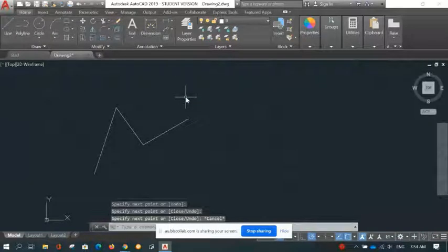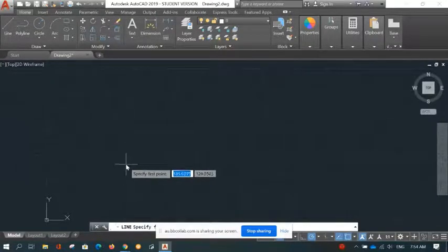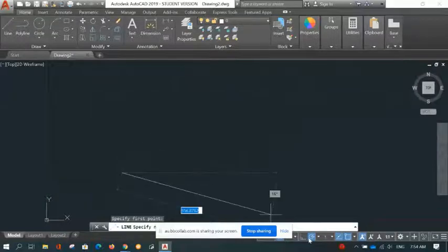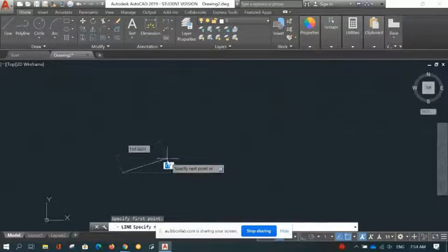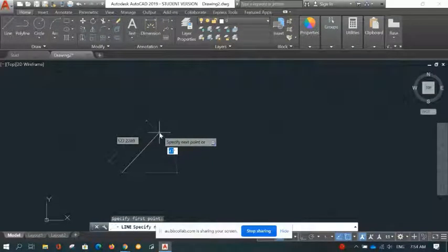But if you're using dynamic input, right, there's a box with blue text or numbers that appears on your cursor. So when you click, it's asking for either distance, right? And if you press tab, it changes into degrees. In this case, you can draw the lines according to the sizes and measurements that you want.